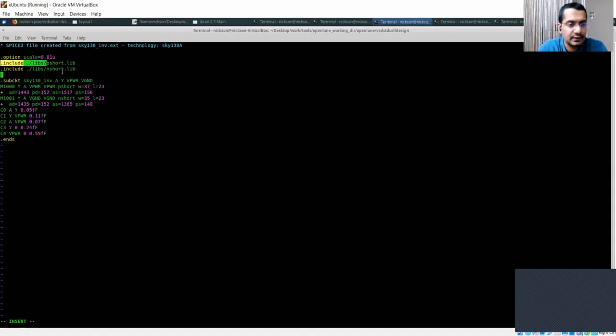So these two files are included. We will comment out this, because we are trying to input the controls and the transient analysis in this netlist, so we will put it as a comment.